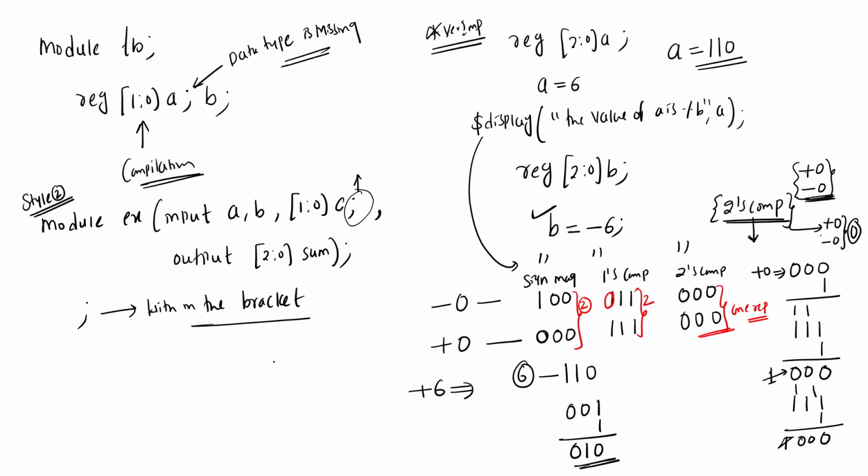See here, 0 1 0 means here you need to add 1 over here, but actually it will not carry, because the size is 3 bits only. So 1, 2, 4 and minus 8. Minus 8 plus 2, how much? Minus 6, no? So like this it will display. If you are giving a negative number, it will display in terms of two's complement.